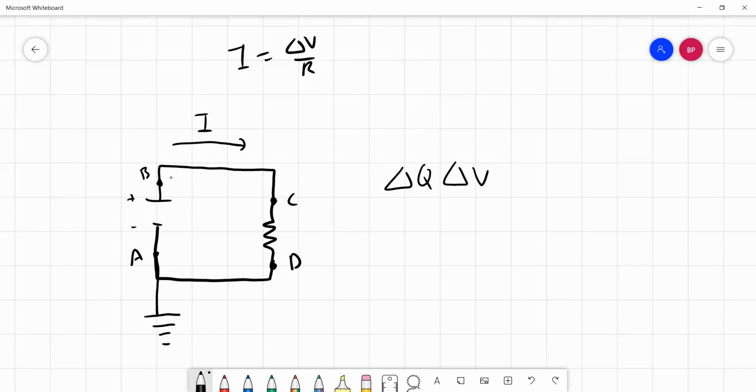Okay. Now, we know that wires do have some resistance, but we did an example last time and we calculated that the resistance of a 1 meter copper wire was significantly less than 1 ohm. So an actual resistor here is going to have a whole bunch of resistance, which essentially means that we can neglect all of the resistance that's in our wire everywhere else.